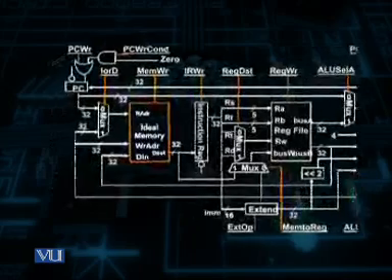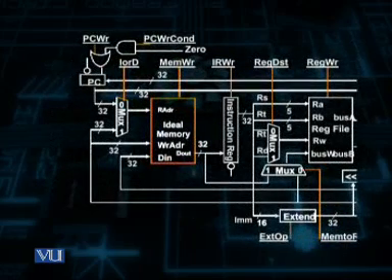However, considering this particular multi-cycle design, you can see that, with the help of the yellow path, in cycle 1, which is the instruction fetch cycle, firstly, the multiplexer MUX-1 selects its input: its select input I or D is made equal to 0, and the program counter is connected to the memory read address input, shown here as RADR. The instruction is fetched from the memory at the data output.